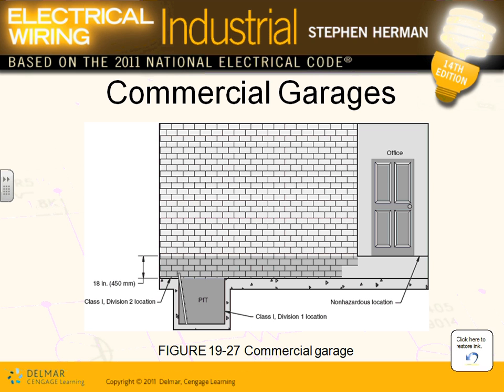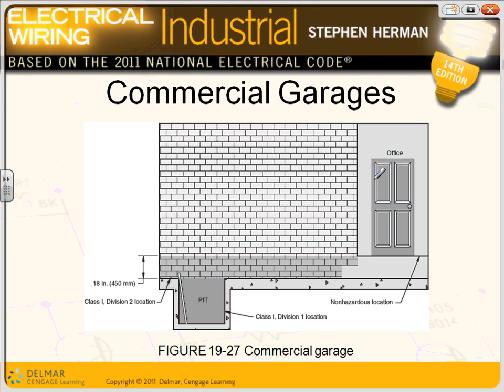Commercial garages. They define a commercial garage, guys, as a garage where cars can be maintained, like troubleshooting and so forth. They go into details about the definition of a commercial garage, but think of it as a place where you fix your car and so forth. If you have a pit in the commercial garage, then this pit is classified as Class 1 Division 1. These are the places where they work on your car. This is the type of garages that we're talking about here. This area is classified as Class 1.